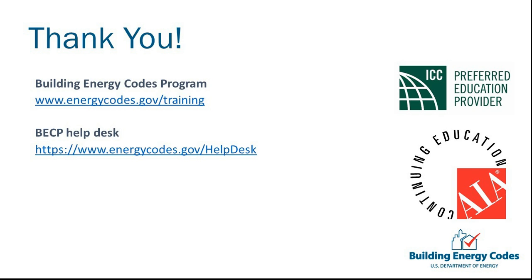Okay, thanks. And I've got a question here for Dick. As part of your discussion, you mentioned TSPR as one of the things that might be coming along in 90.1. And for those that don't know, TSPR is the Total System Performance Ratio, and it's a systems approach for looking at HVAC system performance. It has been most recently adopted by Washington State for HVAC system compliance. But I understand ASHRAE 90.1 has a group that's looking at this approach. Can you maybe tell us a little bit more about what's being discussed?